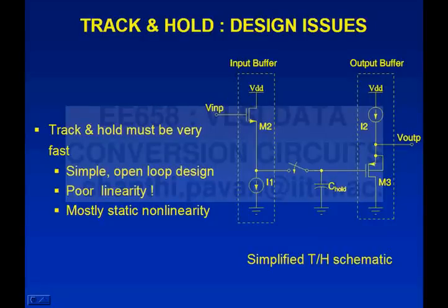So one question is, how can you get better linearity? If you want to take a lousy amplifier and make it linear, what would you do? What is the standard technique that you know? Negative feedback. And when does negative feedback really work? Negative feedback only helps you when loop gain is large. If you want to get large gain, what should you do?